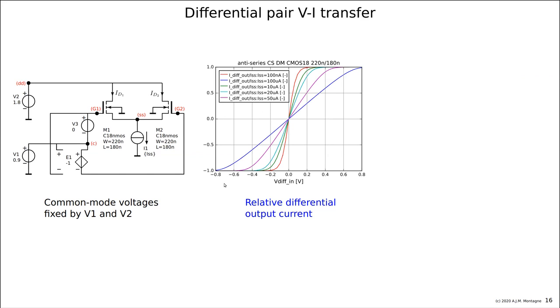Well, of course, it depends on the way of zooming it. There will be, of course, a derivative that is non-zero, but you see that the range now is much wider. It needs a wider voltage range, of course, and the odd terms, of course, are gone in every transition, and the device is more linear. So odd characteristic and increasing linearity with the inversion coefficient. That is important to know. But it is a linearity of the voltage to current transfer. And that is not always the relevant transfer.